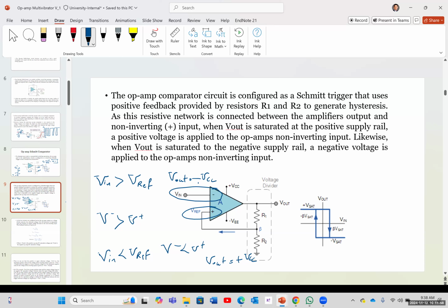So depending on whether our reference voltage is greater or less than the input voltage, you're going to have a positive or negative voltage in the output. This is the reason they call it the inverting amplifier: if you have a positive input, you're going to have a negative output, and when you have a negative input, you're going to have a positive output. So it inverts everything. We went to the last slide. The previous one.